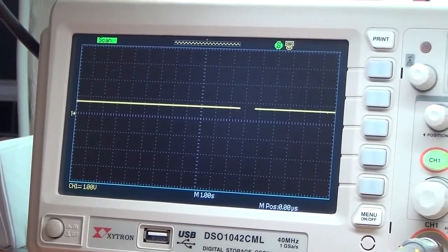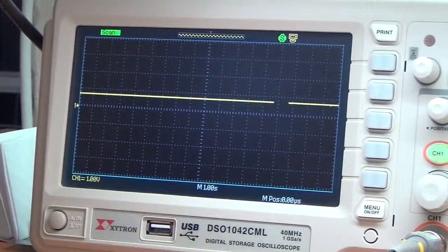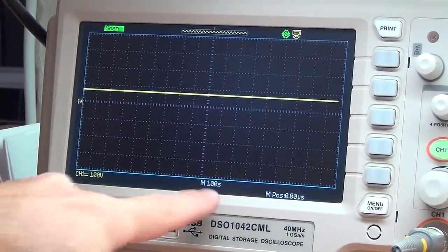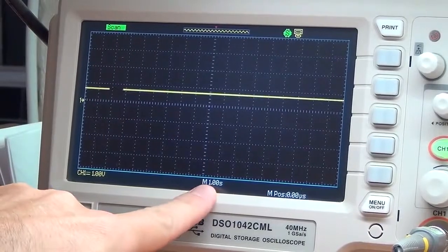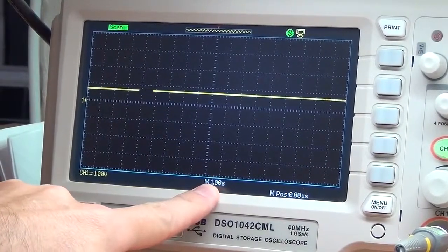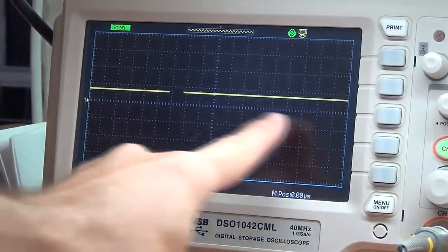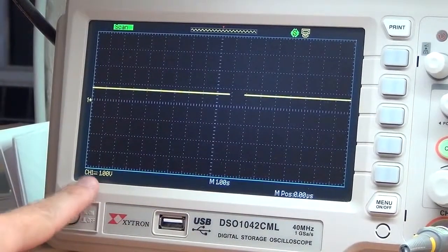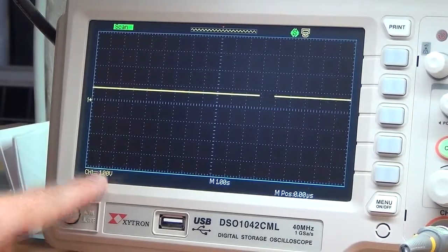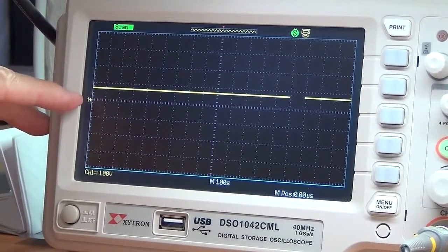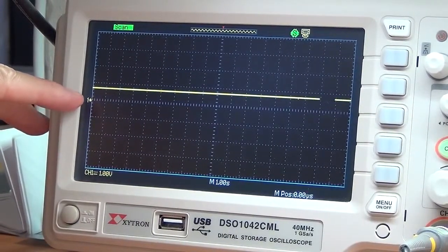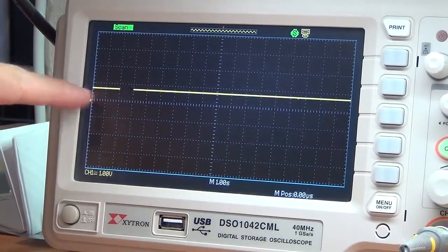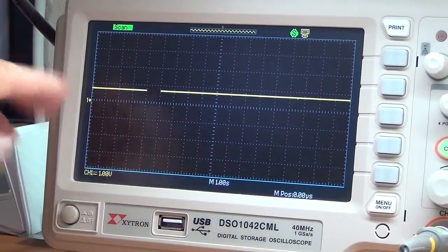Now the oscilloscope is in a kind of scan mode. It's not being triggered by a high frequency signal coming in. I've got my time base set to 1 second per division, so I can show quite a few seconds. You can actually see the scan going across, how slowly it goes across, and I've got it set to 1 volt. So my reference is set at the 0 line. So as you can see, we're just under 1 volt of charge in the capacitor currently.